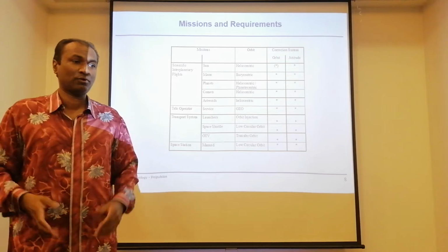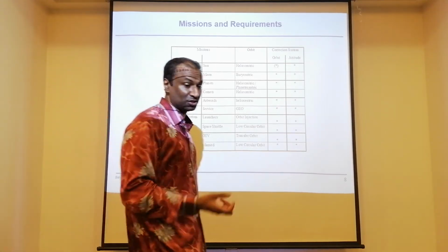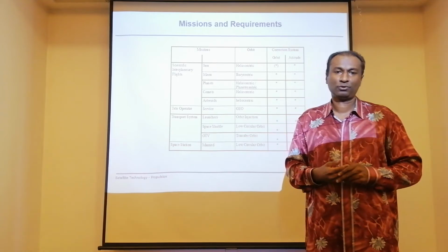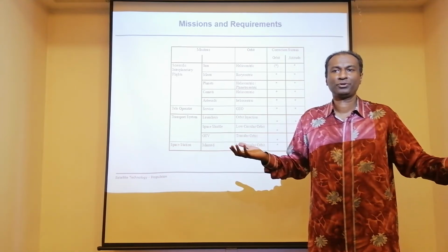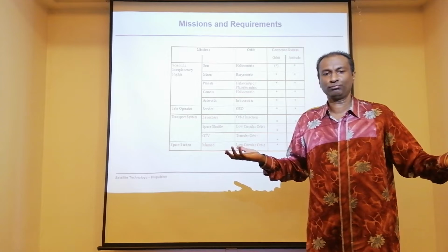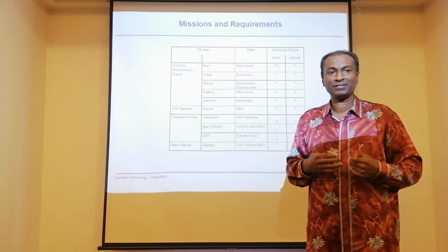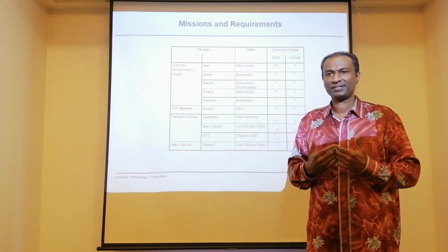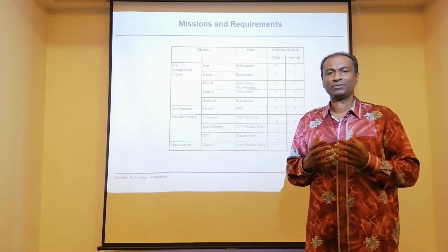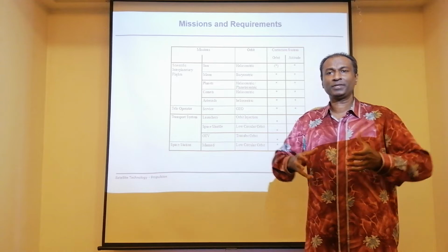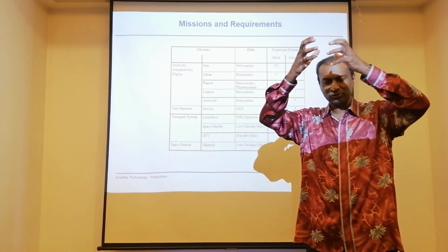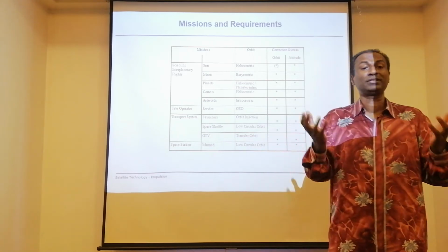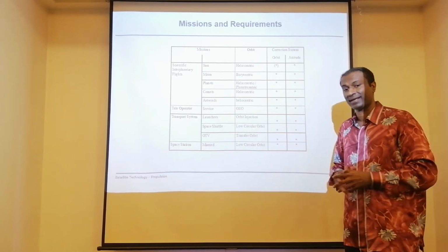But if you have a mission of about a year or two, a low-cost mission, a small satellite mission, a CubeSat, you may not opt for a propulsion system because your lifespan is about a year or two. You will understand this more clearly when you do space mechanics, because there you can see how fast, without a propulsion system, the satellite can drop towards planet Earth. This is because of the disturbances that we talked about, for example aerodynamic drag, etc.